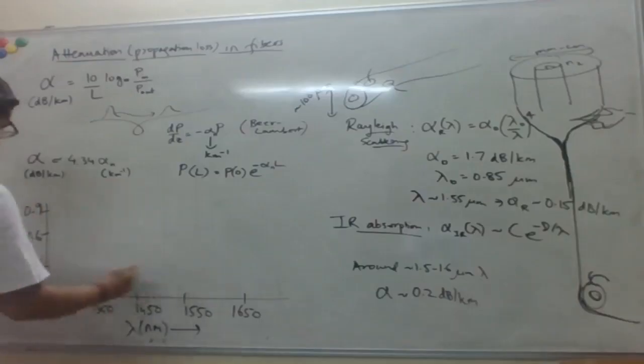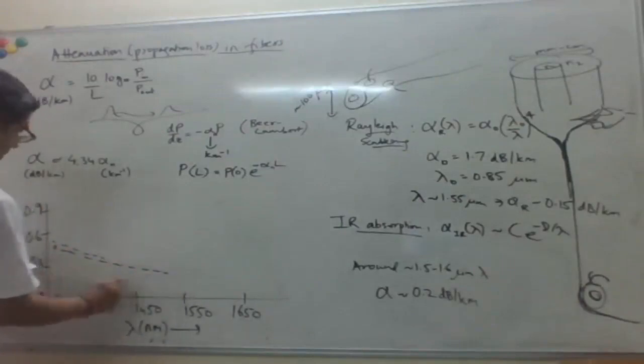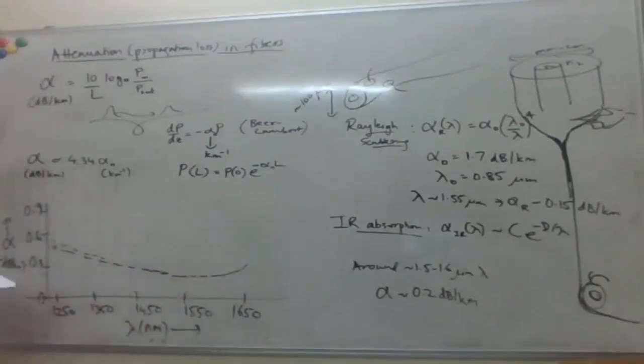So the conventional fibers which have some residual moisture. By the way, that moisture remaining usually is very small, like 100 parts per billion or something. Okay, so that's a very small amount of moisture, but that still has enough absorption to give those loss. Because we are talking about extremely low loss here, right? We are talking less than a dB per kilometer.